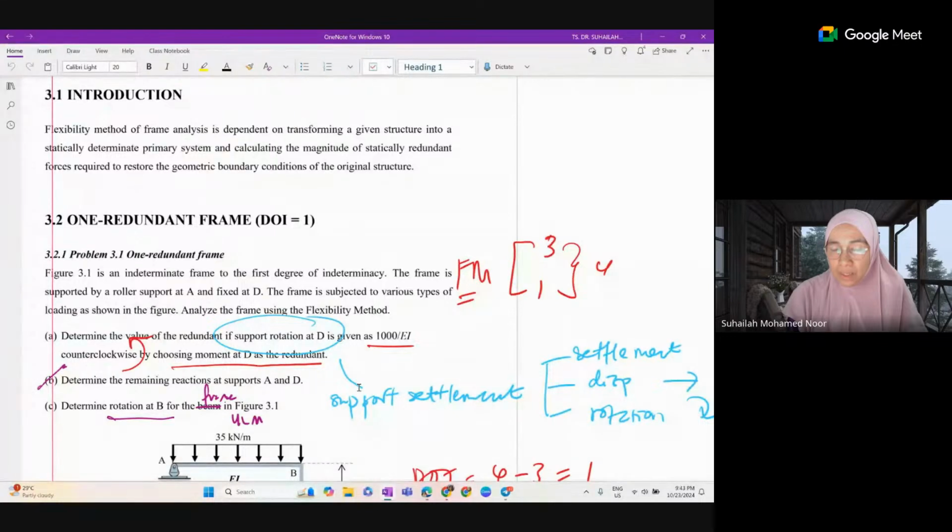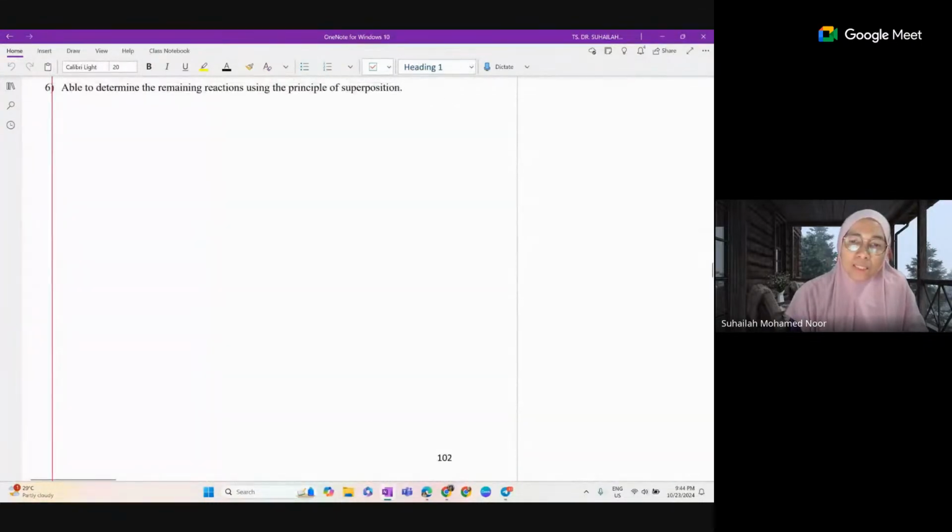Okay, same analysis except the structure is different. Same formula as well. For the displacement, we integrate the moment equation to get displacement. Most important, I want to highlight the effect from support settlement. This effect from support settlement can also occur in beam, in frame, and in truss as well. So this is what we have in the module under topic number 3, frame analysis.